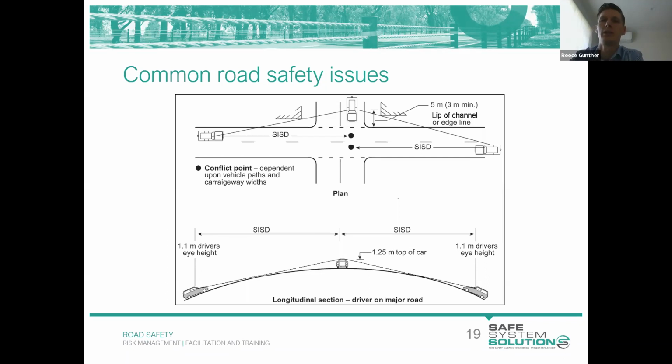That discourages smaller vehicles from using that part of the road, but it also allows larger vehicles to track beyond it. There are requirements, particularly at roundabouts, where this occurs. So if you're going to adopt aprons, I think they were saying that it needs approval by DOT as to the size and location of those aprons, to ensure that we're trying to reduce that lane splitting risk that you've mentioned.